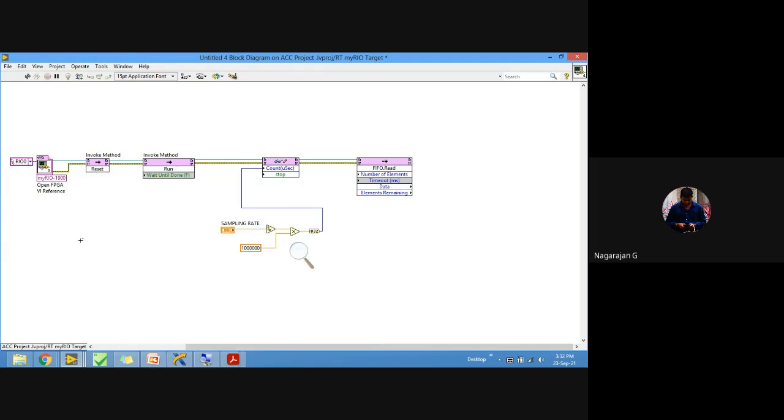So if the write method occurs more often than the data is read, then the FIFO will eventually fill and an overflow condition will occur. In case the FIFO is full, the additional write method times out and data is not written to the FIFO until you get space, until the space is available. The space can be created by reading the data from the FIFO, or by resetting the FIFO memory. If the read method occurs more often than the data is written, obviously a FIFO underflow error will occur.